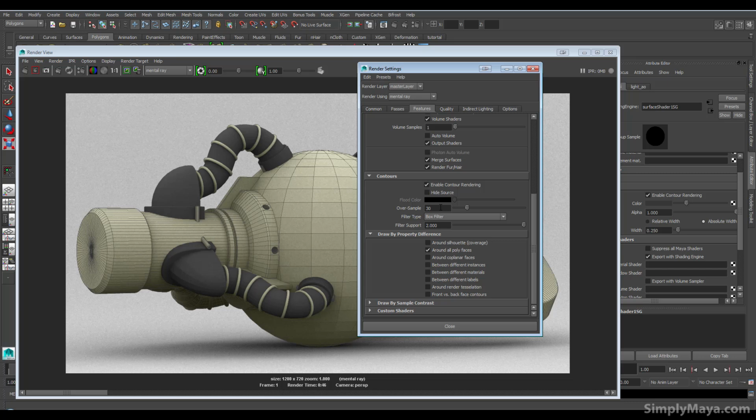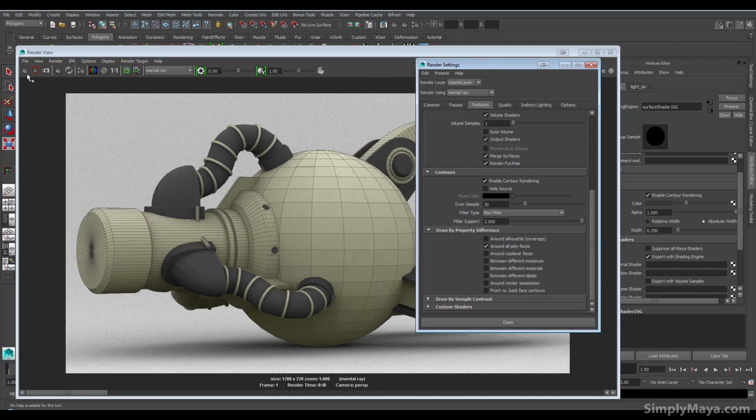Now for a final shot, if time is not an issue, because at 30 it will probably take about a minute to calculate the contour, depending on how complicated it is, of course. So, if you want to spend an extra couple of minutes getting that nice final image, I've cranked this up to 60, 70, 80. Really it's down to you. At 30 should do a good enough job for what we need, and we see here this was 46 seconds.